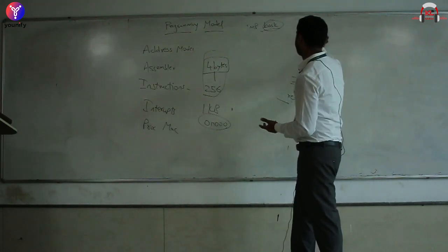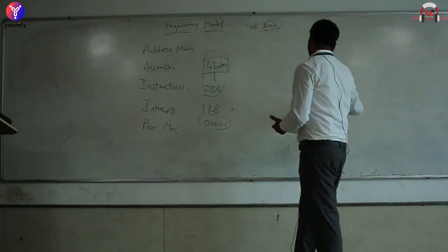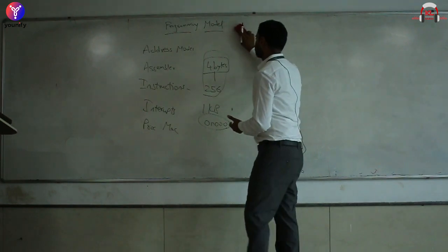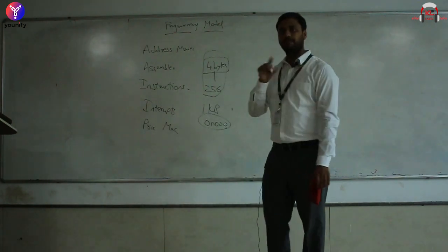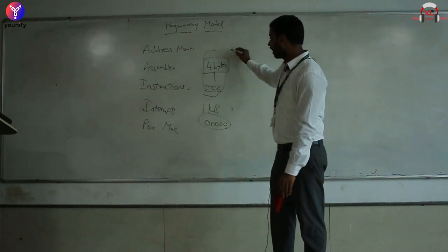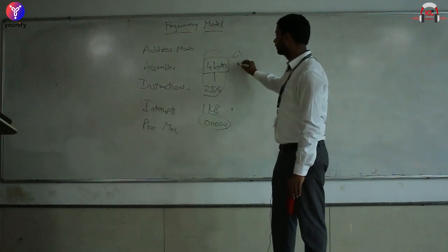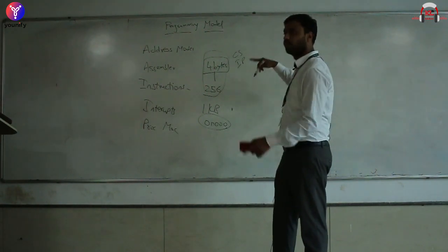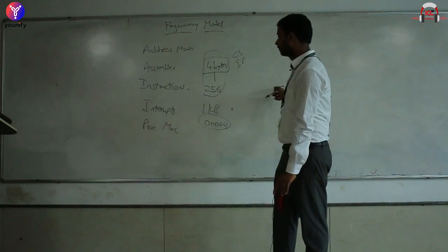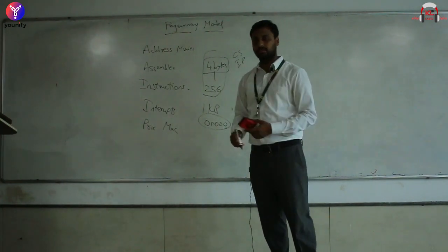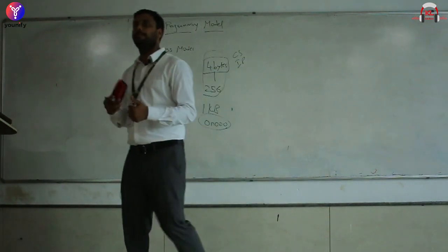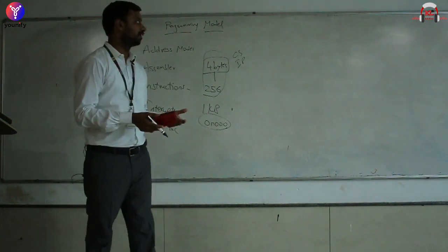So what happens when an interrupt occurs? You push your CS, IP, flags, you figure out what type of interrupt you are dealing with, and go to the IVT, fetch your new CS, IP, go to the program, execute the program, and then come back. So that means we have a pointer of a pointer. What your table is storing is the addresses.